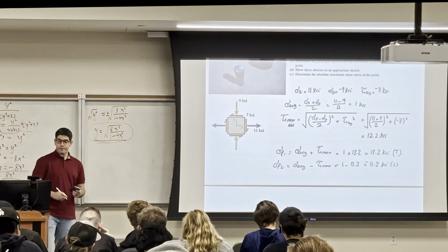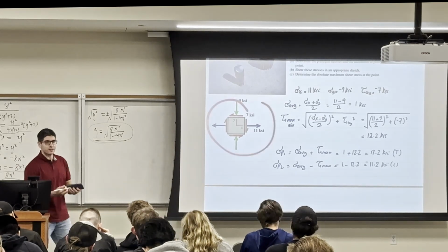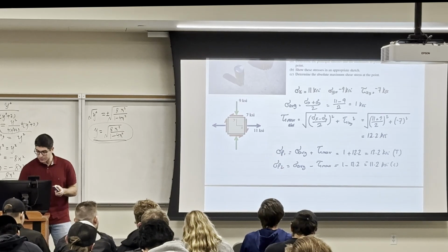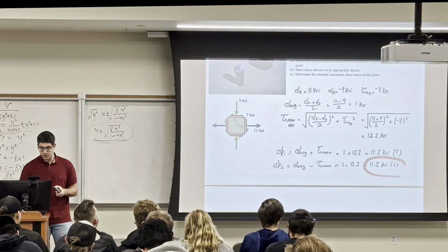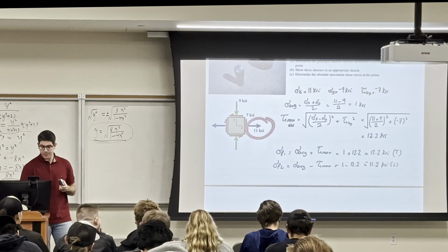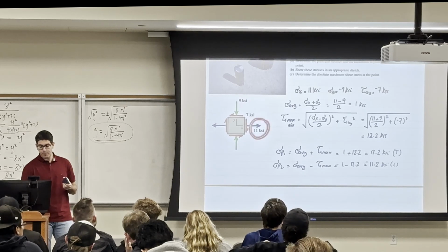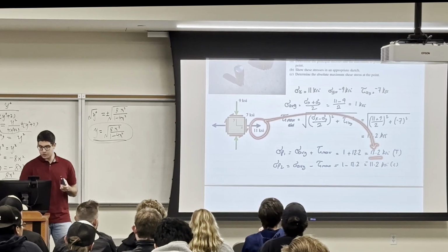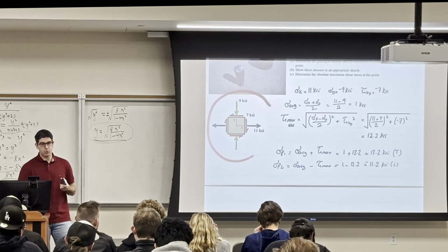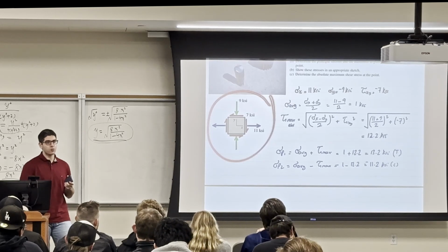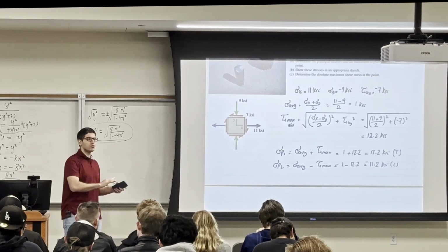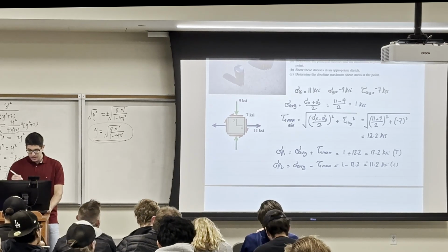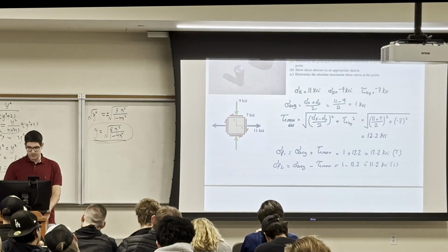Now I know for this element, when I loaded it in x and y, it's going to break with the normal stresses equal to 13 in tension and 11 in compression, which is, of course, higher than the x and y. In x and y, you applied in x 11 KSI in tension. However, it broke at 13.2 KSI in tension. So if you designed your element this way, it is unsafe. That's why we discussed this lecture, so that you can design your structure element or your mechanical element in the angle that will cause the maximum stresses.